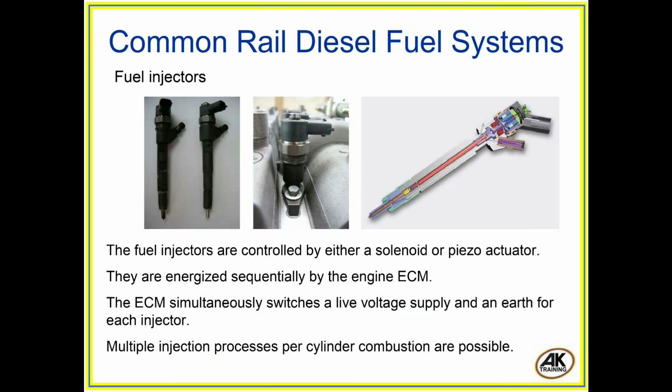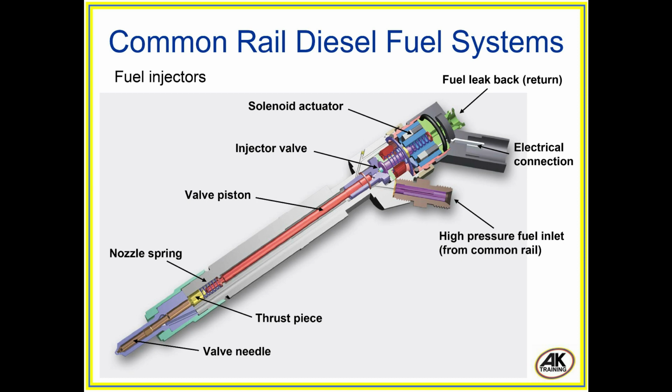Fuel injectors. The fuel injectors are controlled by either a solenoid or piezo actuator. They are energized sequentially by the engine ECM. The ECM simultaneously switches a live voltage supply and an earth for each injector. Multiple injection processes per cylinder combustion are possible.